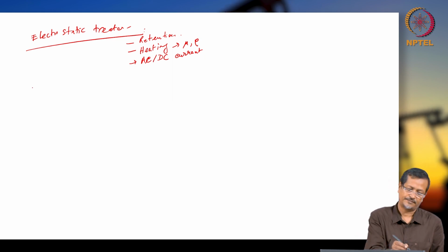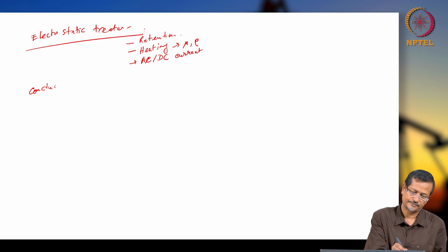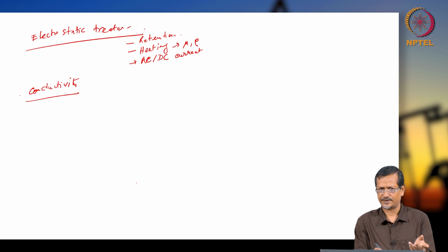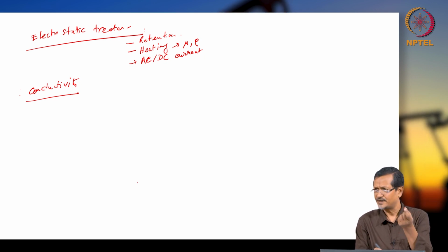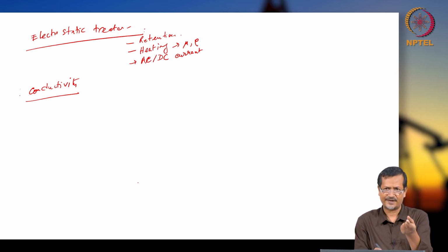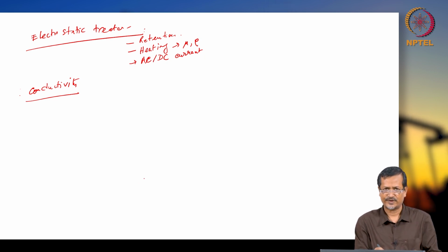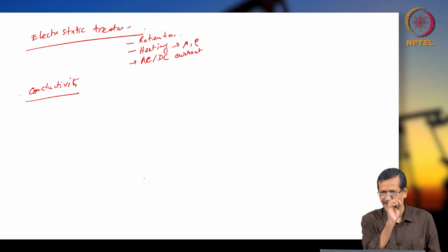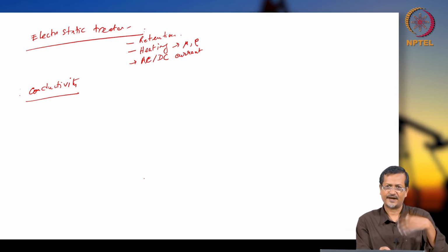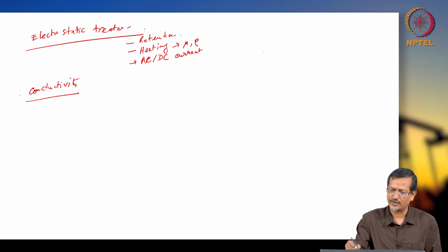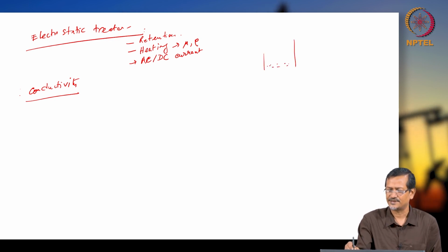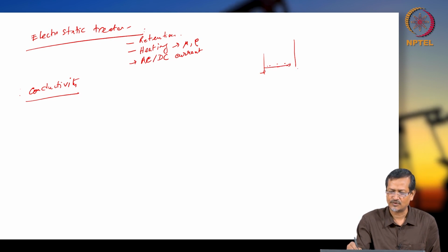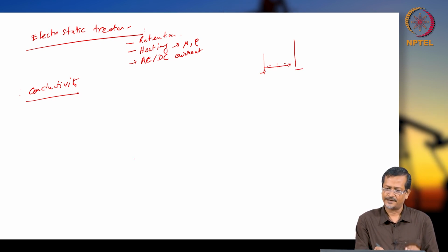Crude oil conductivity. Normally oil will not have any conductivity, but oil will have some ionic material inside, a contaminant you can say. Those will be conductive. So, when ionic material is there in crude oil, the ionic material will be moving and it will allow electric ions to flow. If a very high amount of ions is there, it will create a short circuit. I have two electrodes, and lots of ionic liquid is there, so electricity will try to flow from one electrode to another, right. And if you do not have ionic liquid, then oil is actually non-conductive.